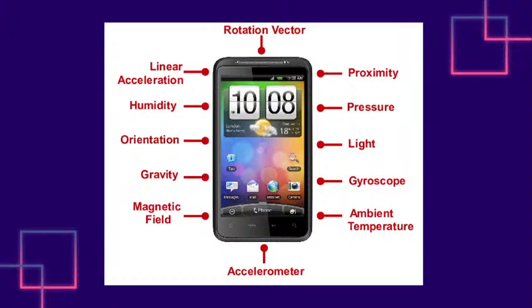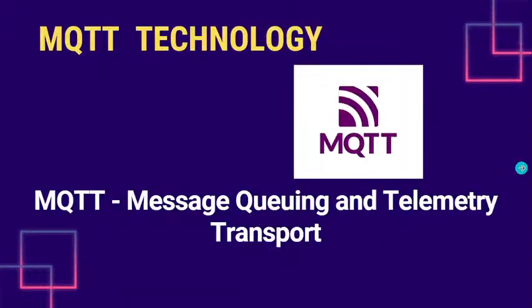So what we are going to do now is get the measurements, parameters, or values from these sensors in the mobile phone, and we need to see these values through our Magic Blocks platform. For this, as the connectivity or gateway between the smartphone and the Magic Blocks IoT cloud platform, we use the MQTT method. The connection mode is MQTT. For the earlier weather station application, we used the Wi-Fi mode. Now for this, we use MQTT.